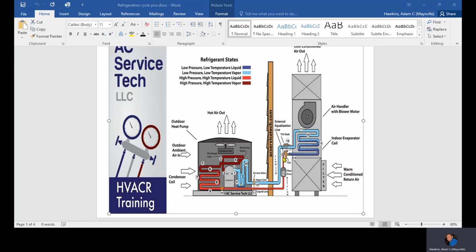It's not going to do anything because it has to have access to 100% liquid all the time. So once the bottle starts getting empty, you start kind of sucking air, and then you have trouble getting the liquid out of the bottom because you've lost your suction. So it's the same thing with this. It has to have a steady stream of liquid. So there's ways that we ensure that that condenser is completely condensing 100%, and we'll get to that later.